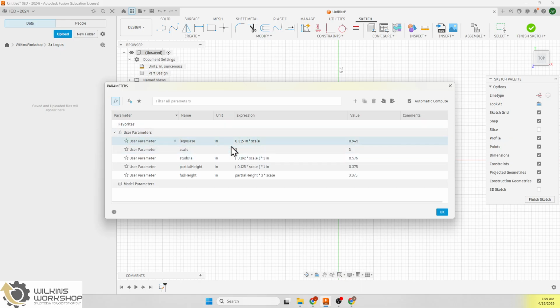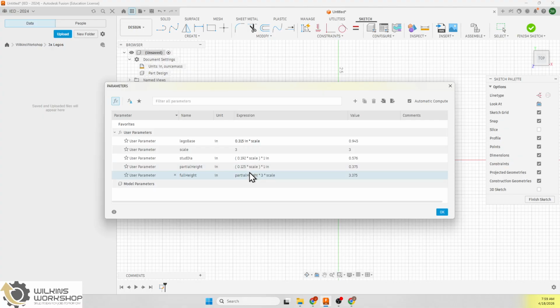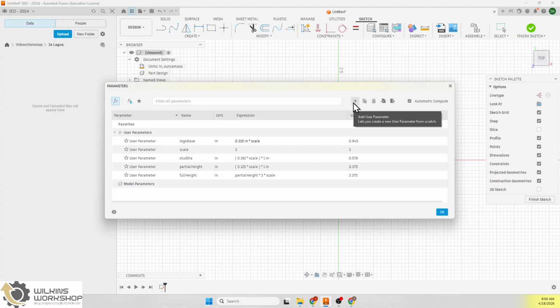These are what we have found through our classroom measurement, that these are kind of the values that we came up with. Again, not every Lego is identical. They're all pretty close. They're injection molded, and it depends on where in that cycle of the mold. Depends on how tight that tolerance is. But for the past 40 years, I can take Legos from 40 years ago and integrate them with new ones, and they fit just fine.